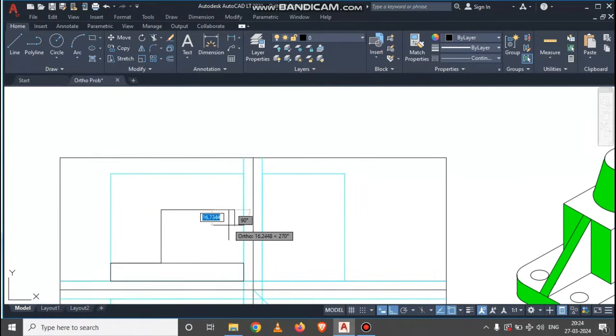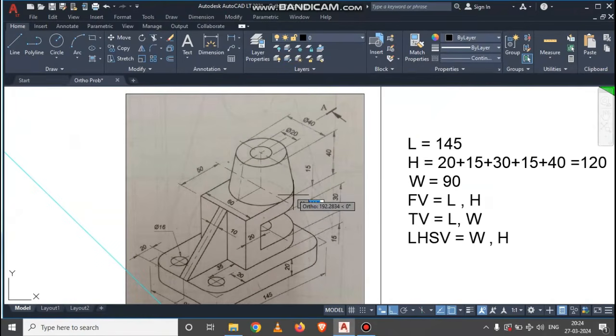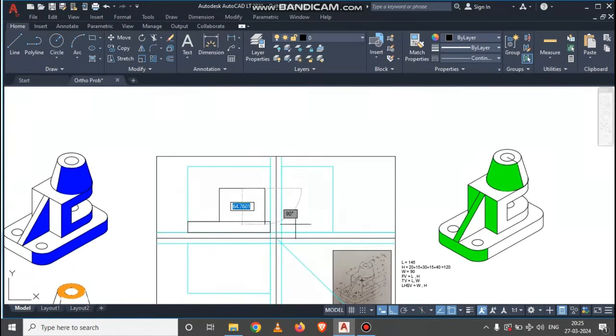Again from that we need to draw the vertical line from this point to this point, and they have given height equal to 15 mm in a downward direction. Again from that we need to draw this horizontal line, and we have to keep this 20 mm distance so that we reach this point, and again from that we need to draw a downward line of 30 mm so that we can have this corner point. Again just draw the horizontal line for the remaining length and connect to this baseline, so that we will have this C type portion in the front view projection.